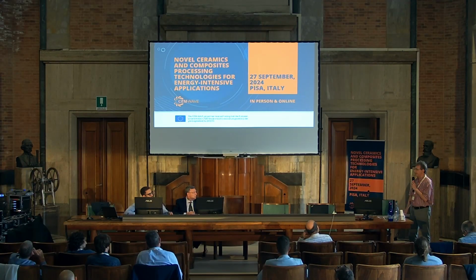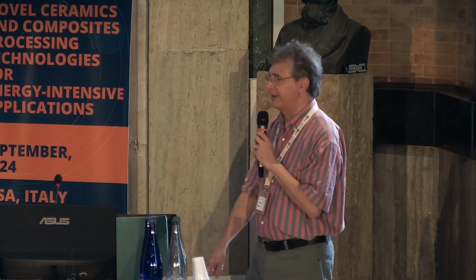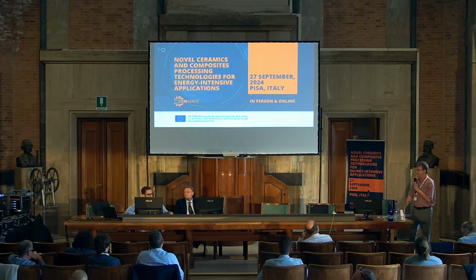So not for these materials, but for instance, for zirconia, we can go from 3D printed to fully dense in 1 hour and 2 minutes. 2 minutes for sintering, an hour for chemical debinding. So we can do that with FDM-based systems, and also with direct writing, and also with DLP-based systems. Using UHS. UHS. Yeah. Okay. Thank you.